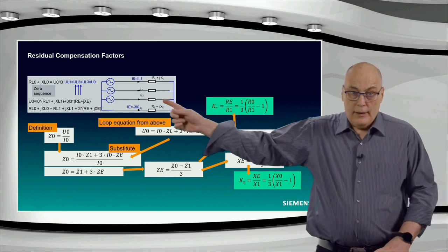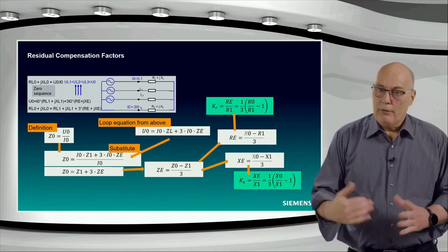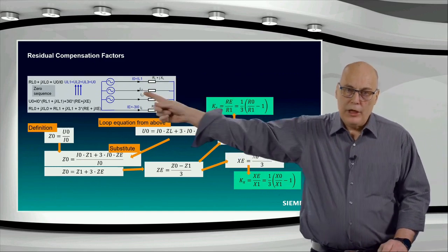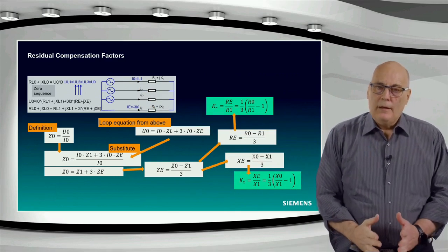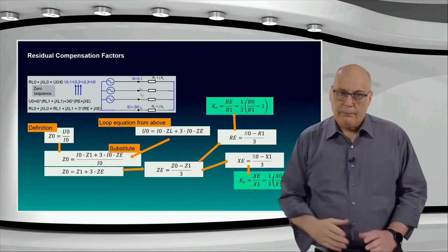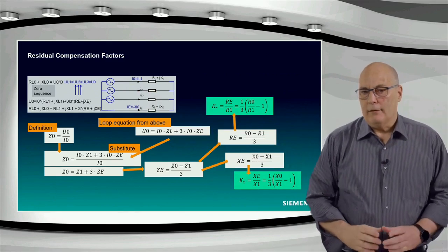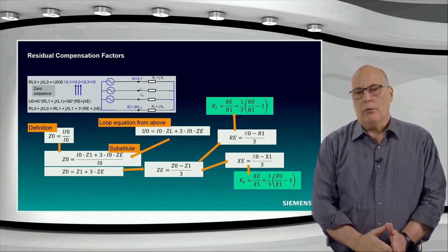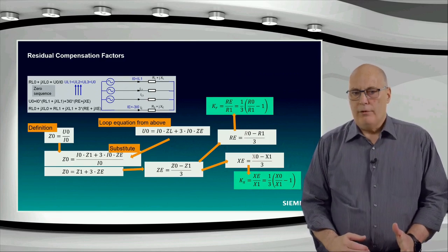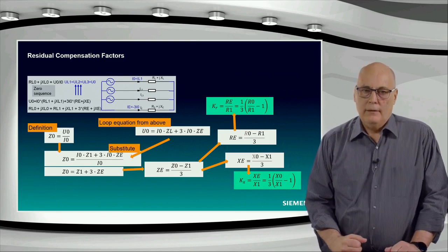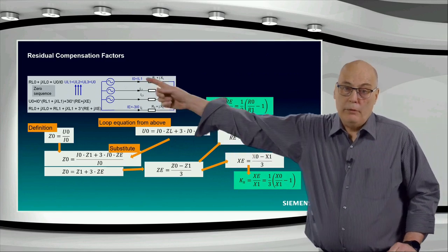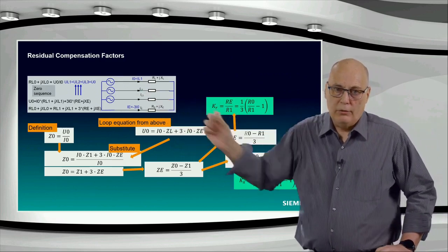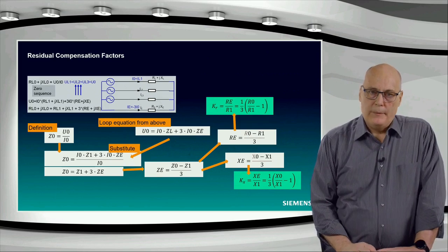So what am I trying to show in this diagram? In this diagram here, I connect my three phases with a short circuit at the end of the line, so to speak, and I inject at the beginning 3 voltages, and the 3 voltages I inject are those 3 blue arrows. They are exactly in phase and identical. So in that case, what voltage is that? That is the zero sequence voltage by definition. The zero sequence voltage means that it is exactly the same in all 3 phases, magnitude and angle. That is a zero sequence voltage. What you could do in this case, you could make a short circuit here because the voltage there is identical, and replace that injected voltage with a single U0 zero sequence.